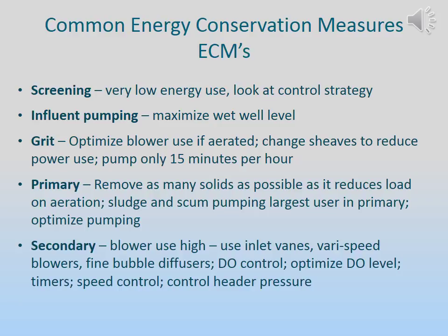Therefore, blower use is high energy. Inlet vanes or valves are typically used to control airflow rates. Options to consider include dissolved oxygen probes and DO control. Consider the use of fine bubble diffusers to get better oxygen transfer. Another parameter to consider is pressure control on the air header, since we know now higher pressure costs energy.